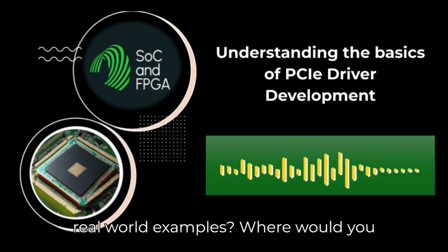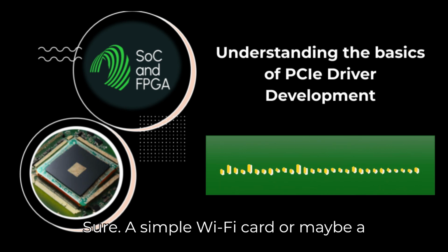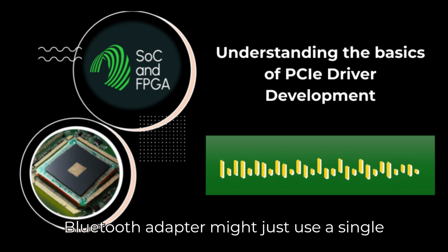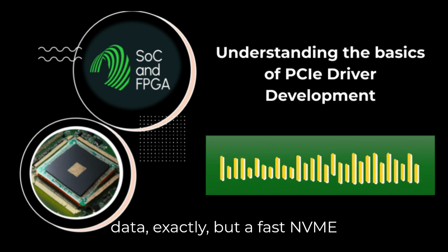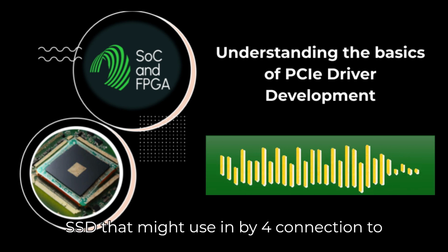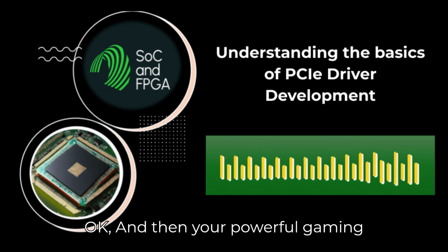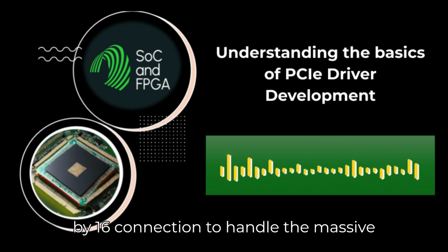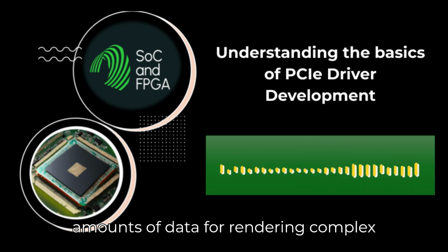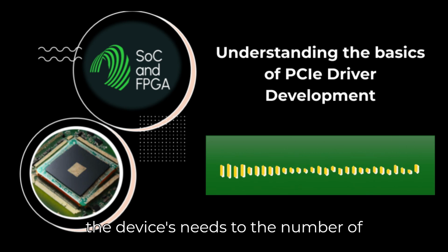Can you give some real-world examples? Where would you typically see an x1 versus an x16? Sure. A simple Wi-Fi card or maybe a Bluetooth adapter might just use a single x1 lane. That's plenty for what it needs to do. Right, not a huge amount of data. Exactly. But a fast NVMe SSD might use an x4 connection to get those really high read-write speeds. Okay. And then your powerful gaming graphics card typically needs that full x16 connection to handle the massive amounts of data for rendering complex scenes smoothly. So it's about matching the device's needs to the number of lanes.